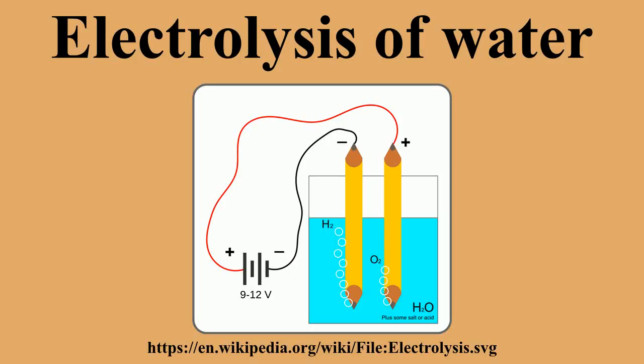If electrolysis is carried out at high temperature, this voltage reduces. This effectively allows the electrolyzer to operate at more than 100% electrical efficiency. In electrochemical systems, this means that heat must be supplied to the reactor to sustain the reaction. In this way, thermal energy can be used for part of the electrolysis energy requirement. In a similar way, the required voltage can be reduced if fuels are reacted with water or oxygen ions. This results in some of the fuel's energy being used to assist the electrolysis process